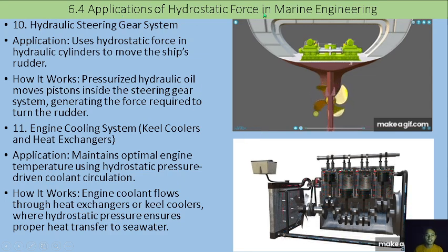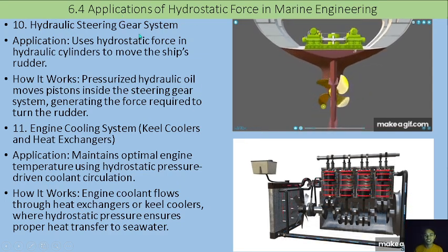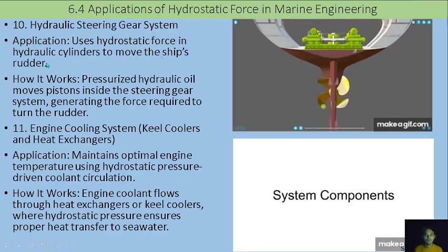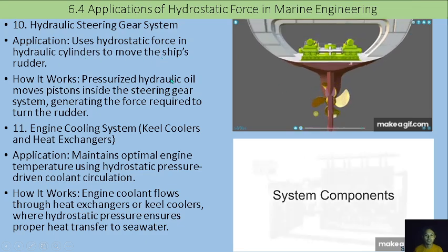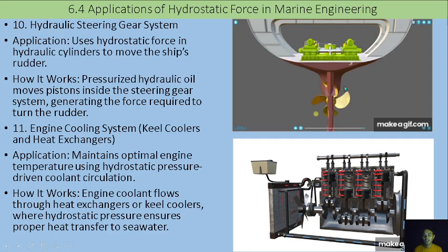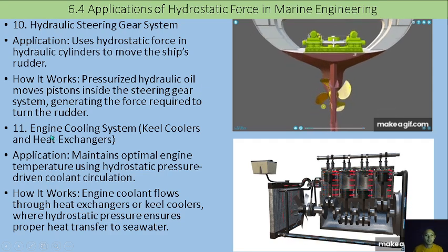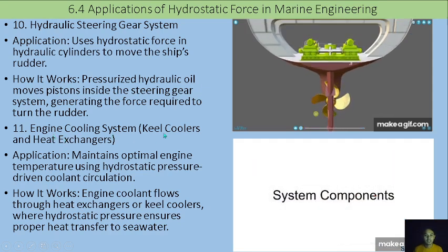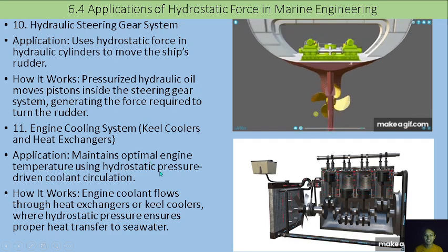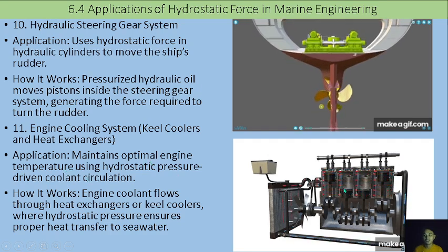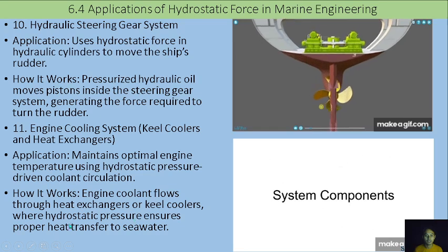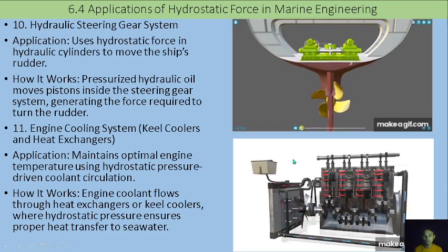Okay, another application of hydrostatic force in marine engineering is the hydraulic steering gear system, as you can see in here. It uses hydrostatic force in the hydraulic cylinder to move the ship's rudder. Pressurized hydraulic oil moves the piston inside the steering gear system, generating the force required to turn the rudder. Another application is for engine cooling systems like keel coolers and heat exchangers. This maintains optimal engine temperature using hydrostatic pressure-driven coolant circulation. Engine coolant flows through heat exchangers or keel coolers where hydrostatic pressure ensures proper heat transfer to seawater or fresh water.